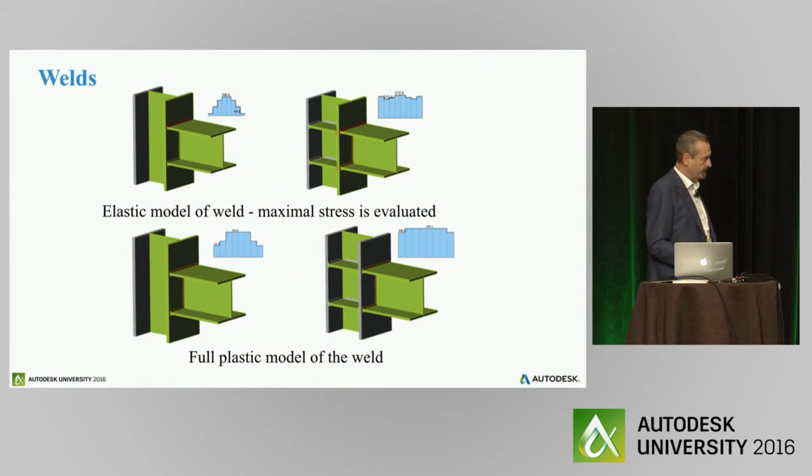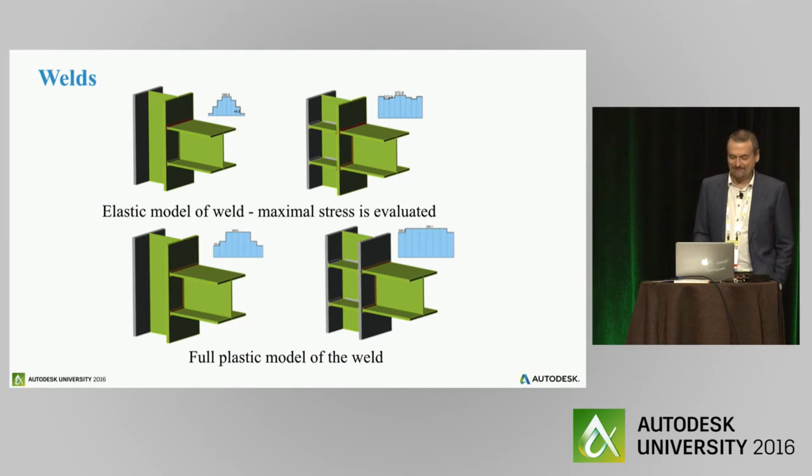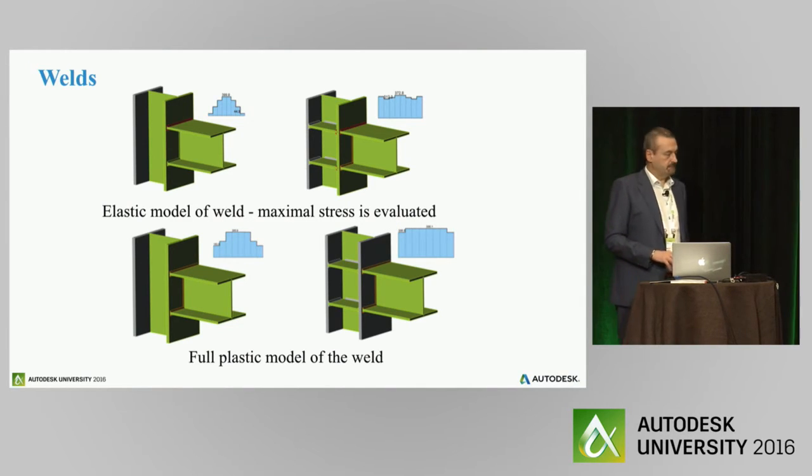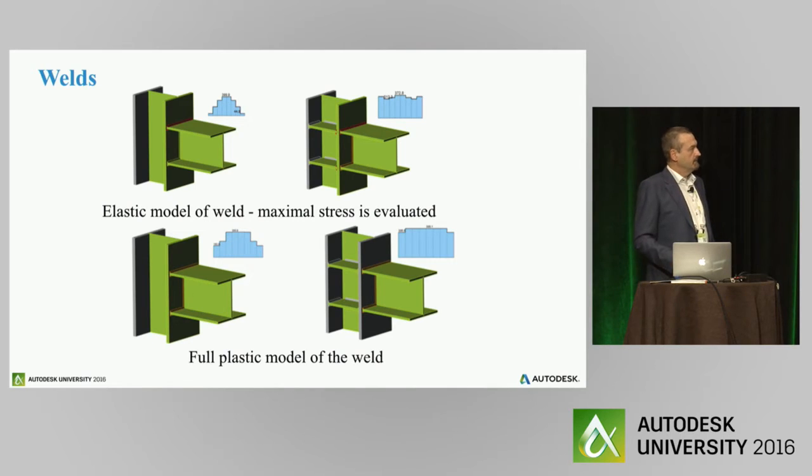Welds are very important part of steel connections. We applied elastic models which are based on these interpolation constraints, and we just calculate forces in these constraints, and then we take stresses and forces in welds and apply checks according to code.